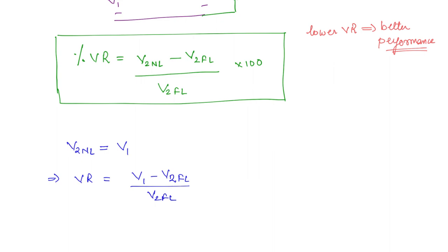Now the voltage drop you can write as I into R plus jX, but we don't want it in terms of the phasor. So what we will do, we can make use of the phasor diagram. If this is the full load voltage, and at a particular power factor angle phi the full load current is having this magnitude, then what will be the drop across resistance? The drop across resistance will be parallel to the current, and the drop across the inductance is going to be leading by 90 degrees,